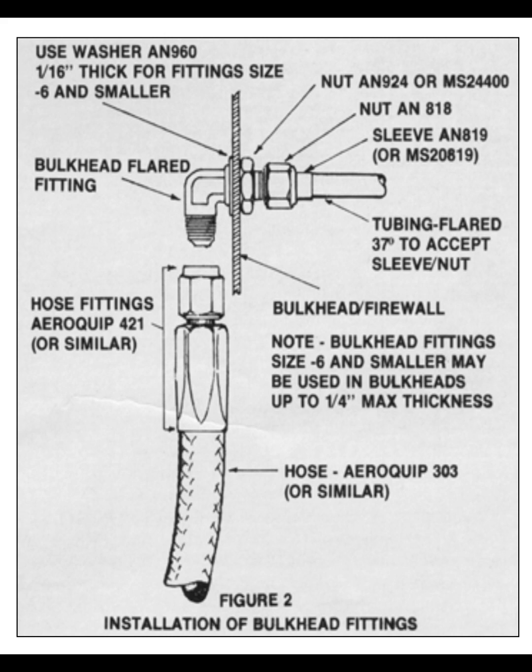What are two kinds of flares used in aircraft plumbing systems? A single flare and a double flare. What is the difference between automotive and aviation flares? Aviation flares should be 37 degrees. Automotive are 45. Aviation, 37 degrees.